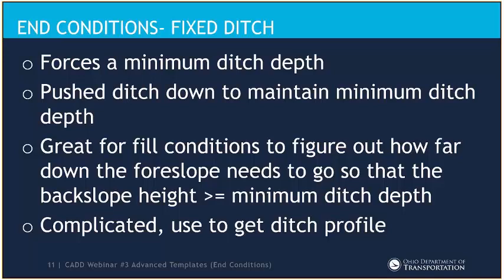This really comes into play when you're in a fill condition that has a ditch in it. When that happens, your ditch might already be above your existing terrain, so there's no way to solve things. It's above everything, so you have to push that ditch down more so it can actually create a ditch. So it gets a little bit more complicated.